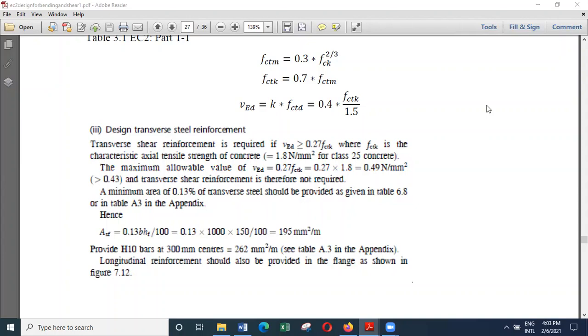But if you look at these Eurocodes, they are written covering all aspects. These clauses are not for one particular type of structure. They cover all the different possibilities. So that's why they have included this particular calculation here. Because if you have only one mat of reinforcement, then there can be failures. But in normal beam and slab construction, we always get two mats of reinforcement, and because of that this kind of failure is very remote. Whereas in the case of a foundation, if you decide to provide only the bottom reinforcement, then this can be a critical situation.